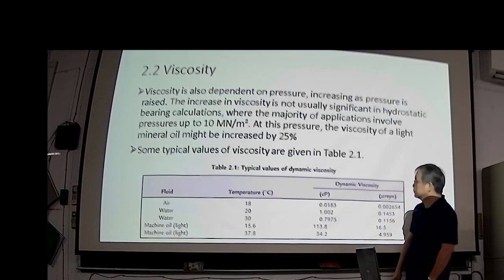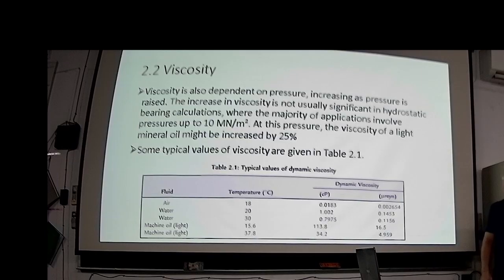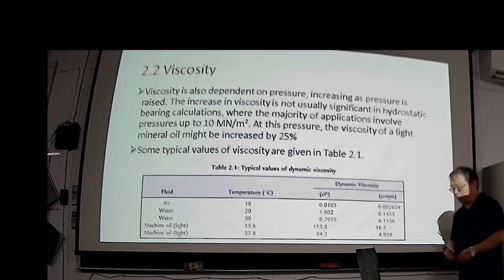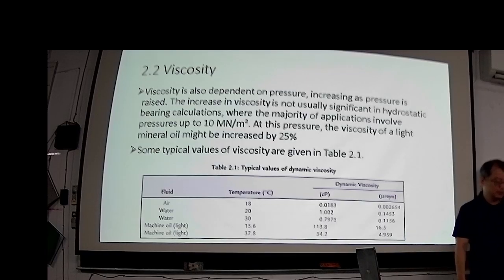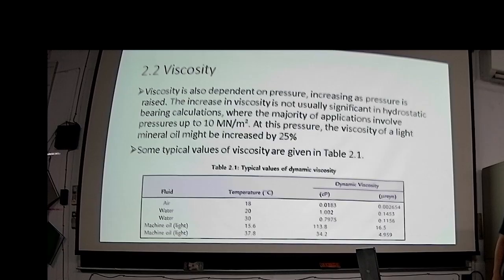So for the viscosity, there is a huge difference between the air and the oil. So the oil hydrostatic bearing will apparently generate a very high temperature rise, especially at high speed.